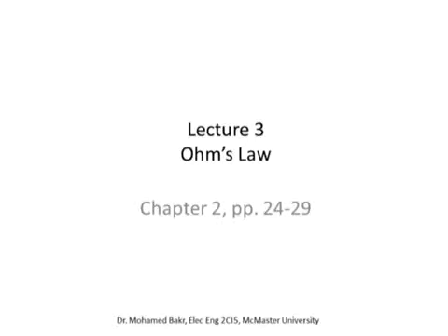Today we'll be discussing Ohm's law, which is a very important law. It relates the voltage and current in resistors. Later in the course, we'll be discussing the relationship between the voltage and current in inductors and capacitors. But for these, it's going to be a differential equation or integral equation, which can be put in both forms. But for resistive loads governed by Ohm's law, it's simply a linear relationship. So we'll show you this in this lecture, and then we'll have a number of examples on how to use this law.